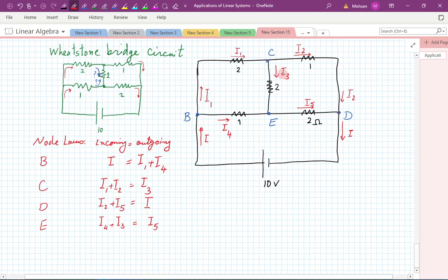Well, yes, it's true that when you are doing a paper calculation, we don't know what the direction of this current is going to be. So we guess or randomly assign a direction. I just draw this arrow, assume that this current is in this direction, and go ahead and do all of my calculations. At the very end, if my current turns out to be negative, it means the assumption has to be flipped. Instead of going this direction, it had to be in the opposite direction.